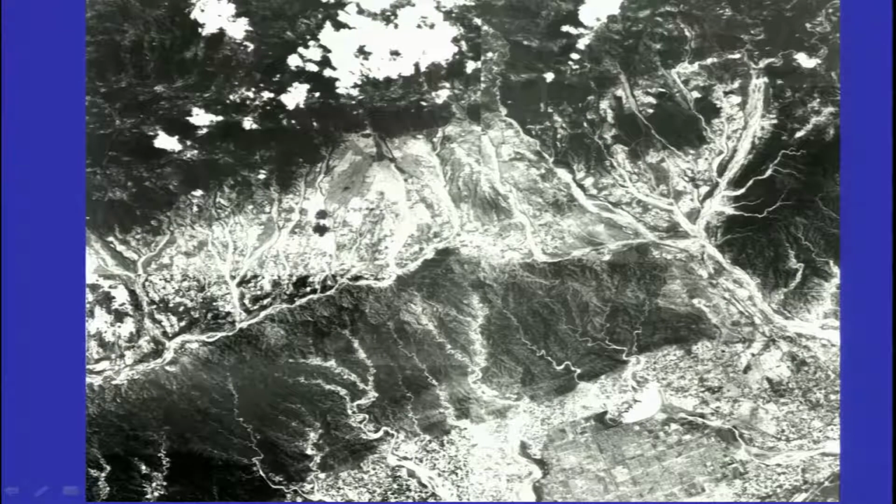And then we have alluvium here as a basin area. Again, we do not have the dense drainage as we see in this blackish portion. This is whitish, in a flat region, and then there is a boundary further going up where we have a different drainage pattern. Here you have meanders, whereas there you have almost straight channels, which you can classify as parallel channels, or parallel drainage, developed over the slope.